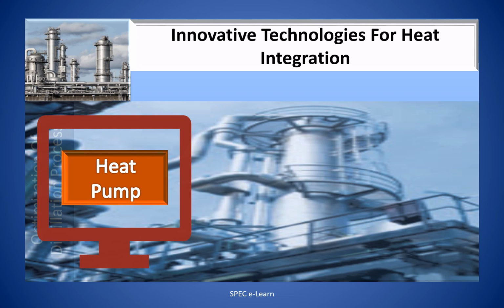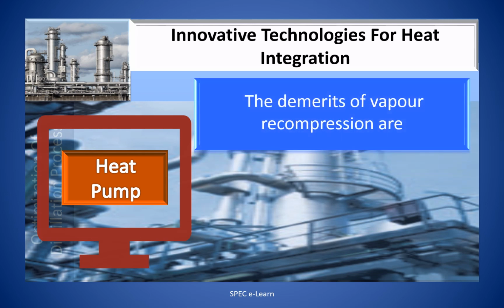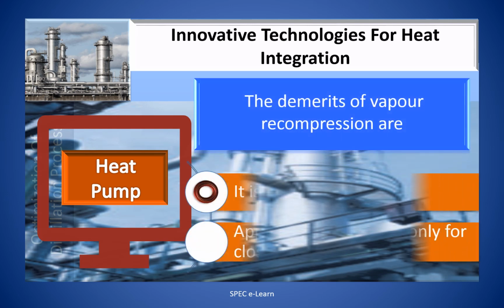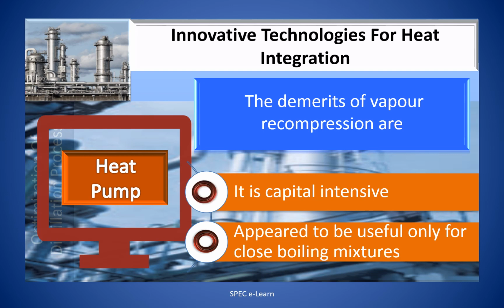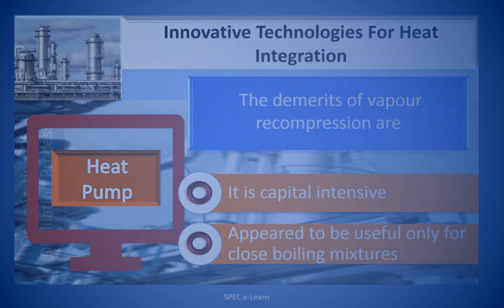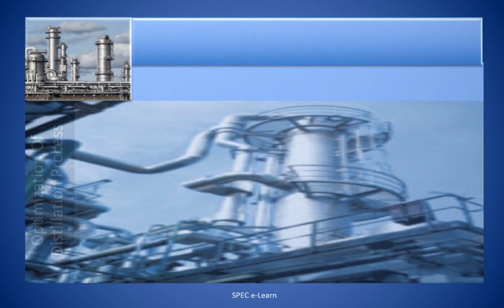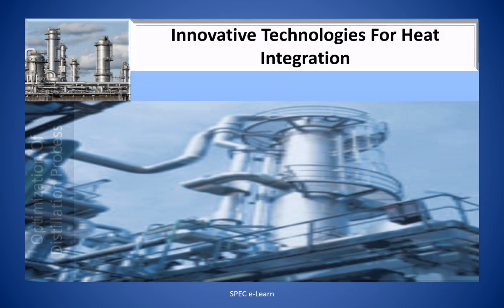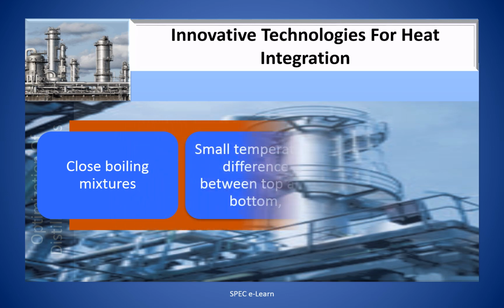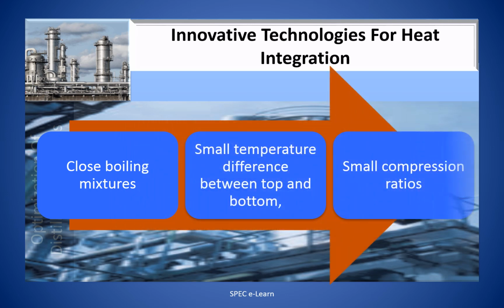The demerits of vapor recompression are that it is capital intensive and appears to be useful only for close boiling mixtures. Close boiling mixtures means small temperature difference between top and bottom and hence small compression ratios.